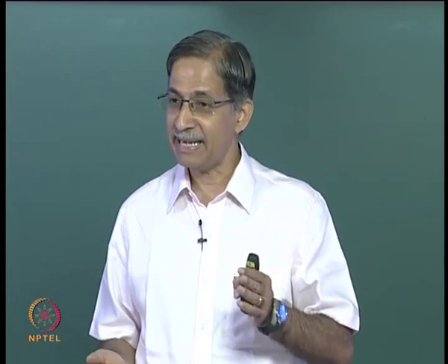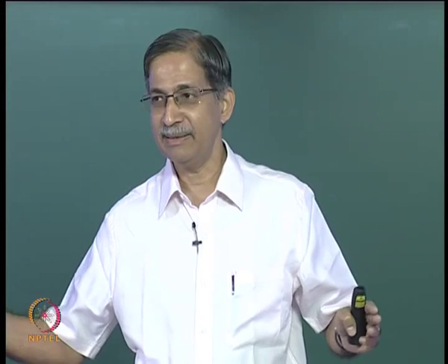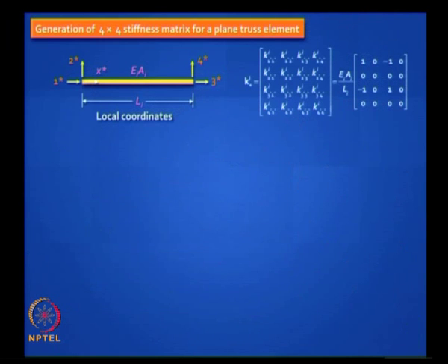So these are the easiest kind of problems you will get. You do not have any inclination theta as you would get in a truss or in a frame. So in a system where you have line elements, the problems are very easy. The transformation matrix is always an identity matrix, so it simplifies your calculations tremendously. Is it clear? Okay. Now let us look at the 4 by 4. We have done this earlier, so can I go fast on this?